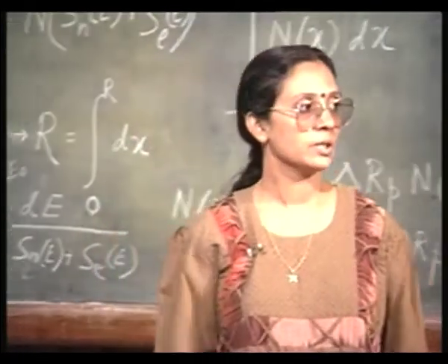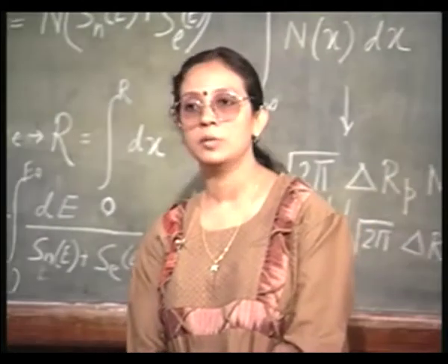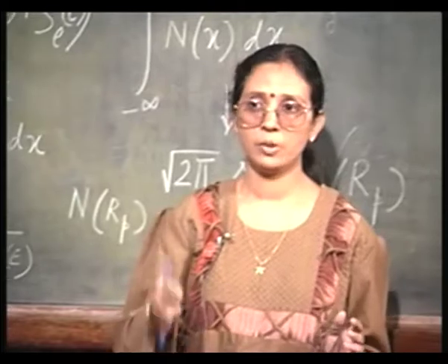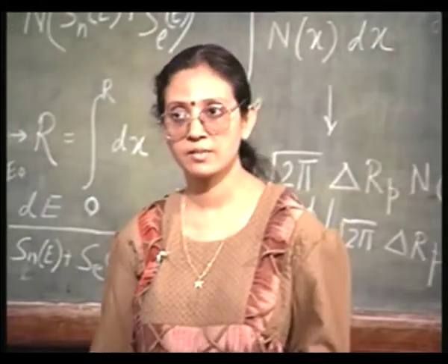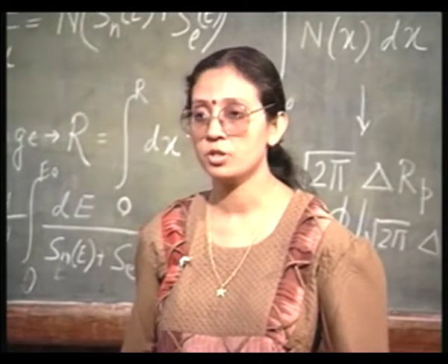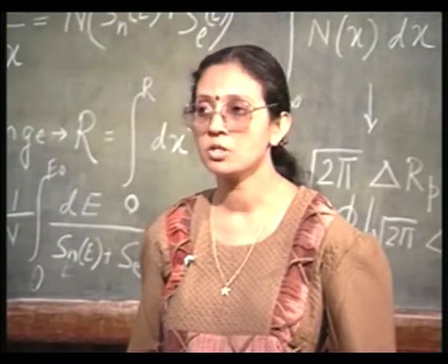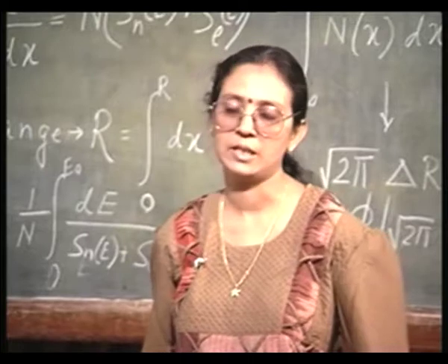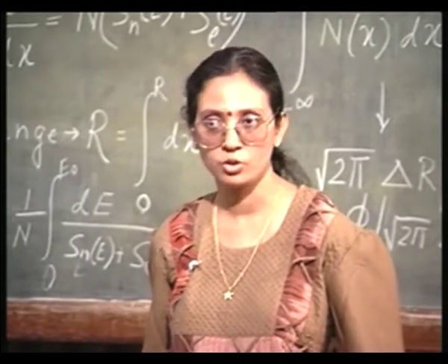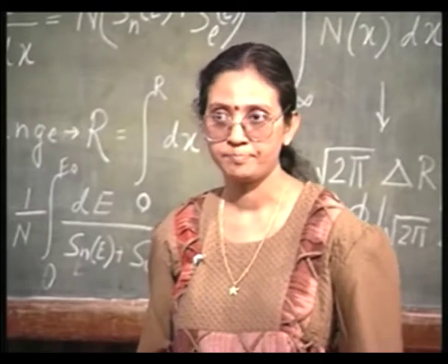Okay? So, these are quite commonly done: implantation through oxide, implantation while misorienting the silicon surface, and prior to implantation a self implantation to amorphize the substrate so as to reduce the effect of channeling. Not merely the effect of channeling, there are other advantages also which we will discuss later.